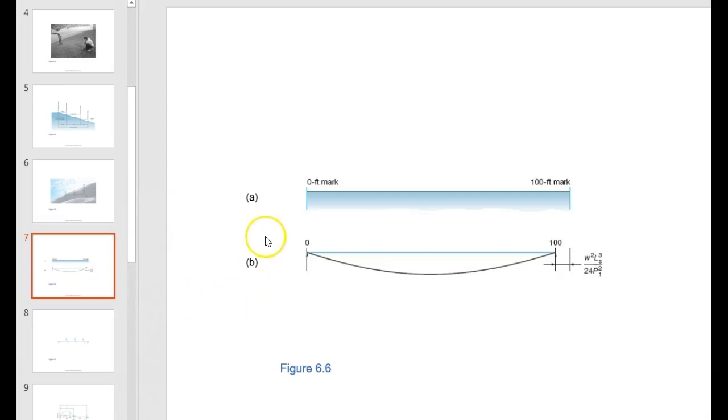Now, this is a diagram of the idea of sag, which we talked about, that catenary that gets formed when you pull a tape, and why you have to compute sag every time you pull a tape. In other words, if you have a 300-foot pull, your sag is going to look tremendously larger than if you have a 100-foot pull. And so it doesn't add together. It's actually based on the length that you pull times itself 3 times. So length times length times length. So you need to compute that catenary based on the length that you actually pull rather than the total length of the measurement.